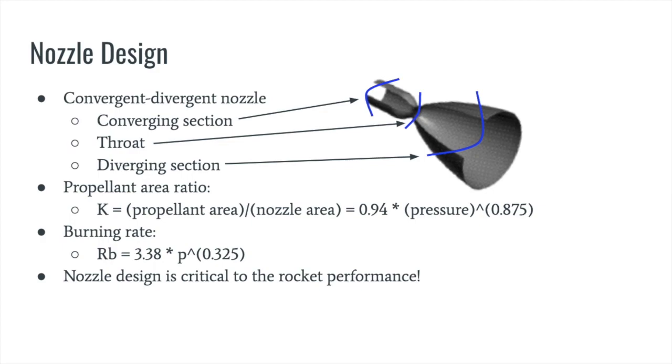This means maximum mass flow rate through the nozzle is determined by the throat area and occurs when the ejected gas's velocity is equal to the speed of sound, or Mach number 1 at the throat, so we use this for our assumption as stated earlier. However, our calculated average velocity is clearly higher than the speed of sound. This is because the next part of the nozzle, the diverging section, accelerates the gas past the speed of sound beyond Mach 1. The exit section of the nozzle is also usually designed to make the exit pressure equal to the atmospheric pressure, which reflects our other assumption.